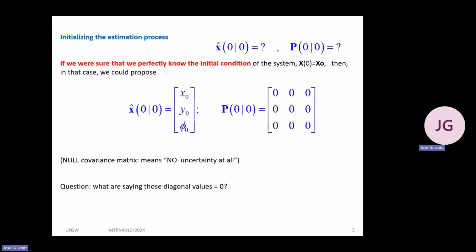So that is the initial time, time 0. We are talking here in terms of discrete time. So we need to have an initial expected value and an initial covariance. If we know our initial condition very well, which is the case in project number 2, because the data set which we are using for playing back, repeating the experiment, tells us with certainty what the initial pose was.